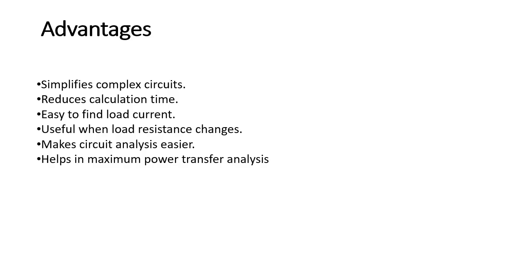I am repeating these advantages one more time. It simplifies the complex circuit. It reduces the calculation time. It is easy to find out the load resistance. It is useful when the load resistance changes. It makes circuit analysis easier. It helps to find out the Pmax, that is, maximum power transfer analysis, on the basis of this Thevenin's theorem.